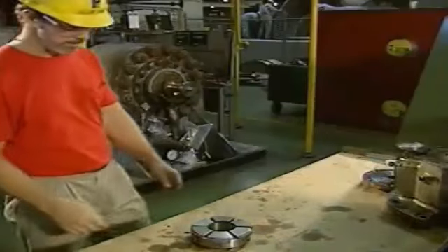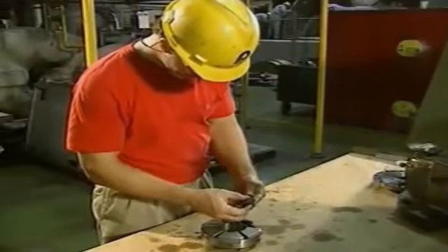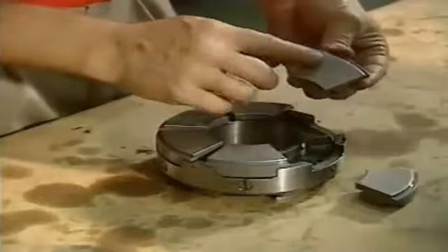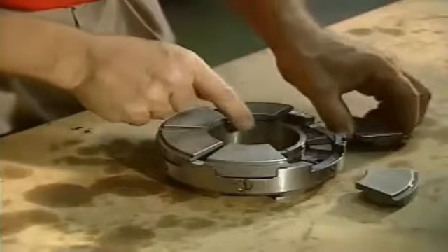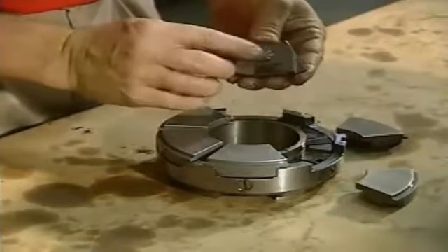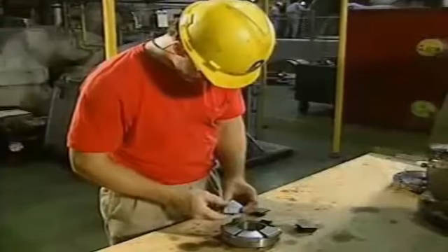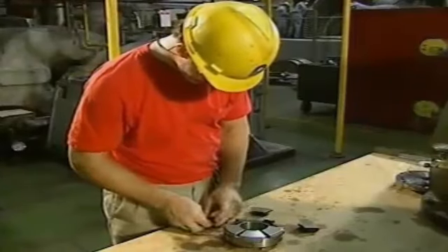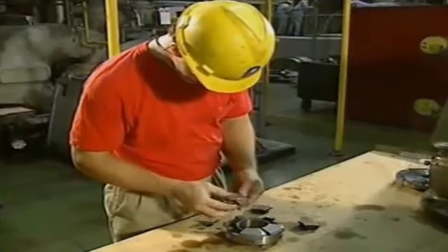The mechanic inspects the thrust shoes next. He removes each shoe from the outboard bearing and carefully inspects it for signs of excessive wear. If any shoe in this type of bearing shows signs of excessive wear, the entire set of shoes must be replaced. If only one or two shoes were replaced, the new shoes would be thicker than the old shoes and more load would be placed on the thicker new shoes. As a result, the new shoes would wear out more rapidly than they would if the whole set were replaced.